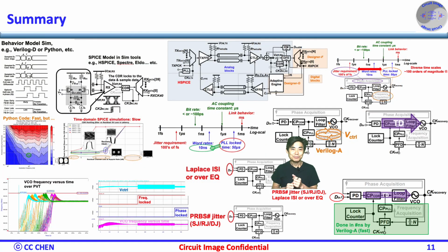Here is the summary of the efficient SPICE simulation techniques for bang-bang CDR verification. There are a few efficient tricks to accelerate CDR development. For example, the VCO servo gives us nanosecond level frequency locking. PRBS makes jitter stress testing easy and flexible. Laplace filters model channel distortion with clean tuning. VCVS gives precise control over latency.